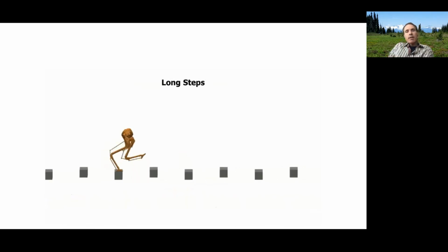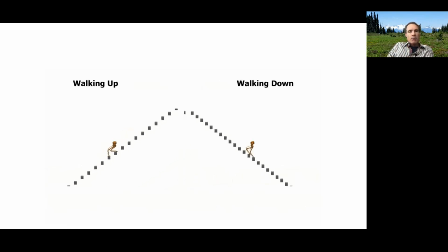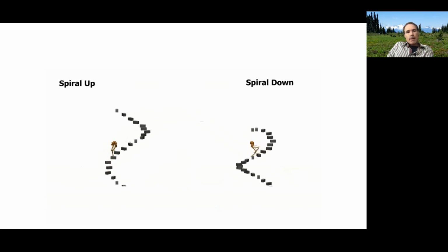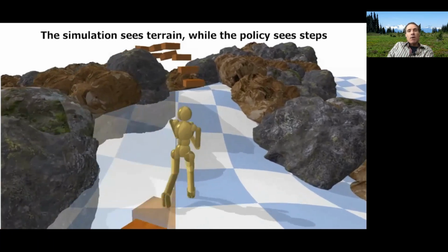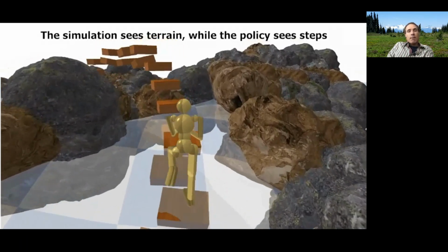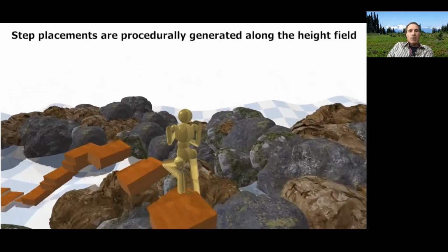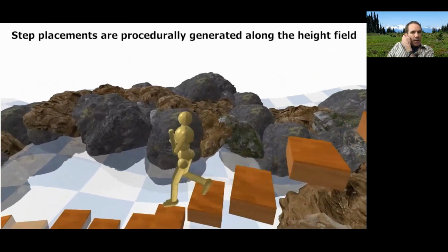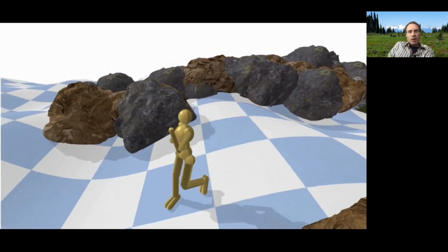And we can also run the same pipeline. This is running with the Agility Robotics simulator for Cassie, with an accurate dynamic model for Cassie, doing a variety of crazy motions. And again, this is all working with the two-step horizon. So if we can tell it where to step, that means we can also walk on variable terrain, by just hallucinating some virtual steps on the virtual terrain, and so these characters can really walk up and down and on all kinds of terrains.